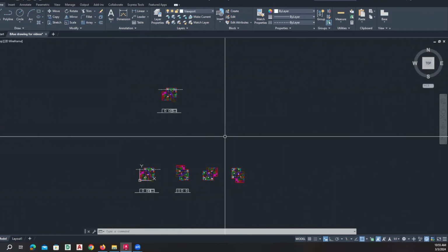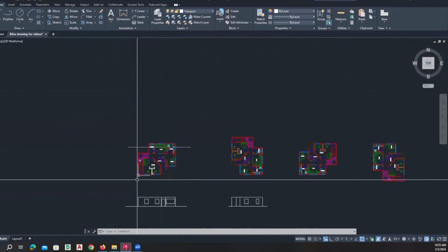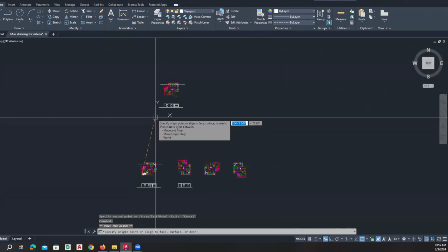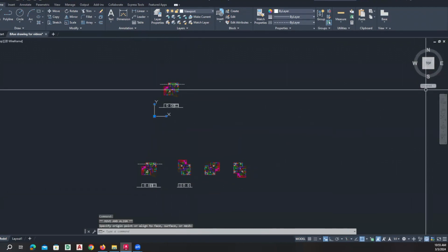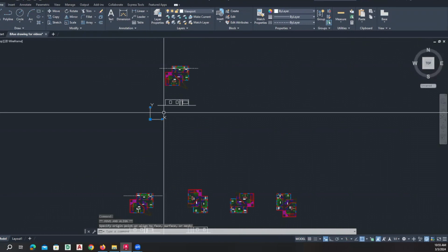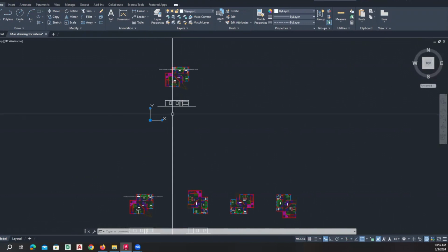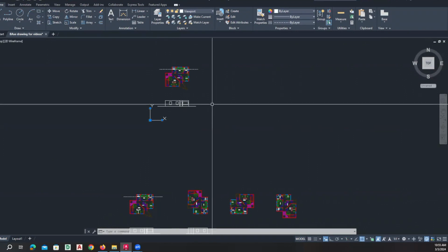And what we can also do is take that UCS and we can move it. And if we move it to another location, let's say here, it becomes a user coordinate system because I moved it, right? The WCS is always oriented the same way, regardless of what happens. Once I move it, it becomes a user coordinate system, a UCS, because I changed it, right?